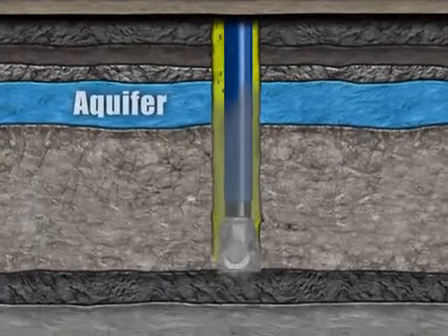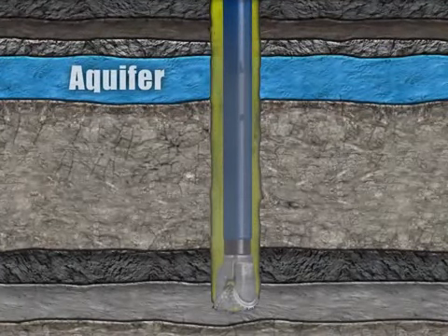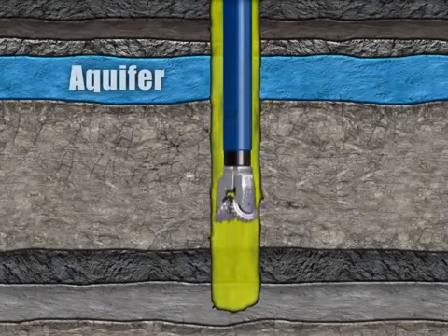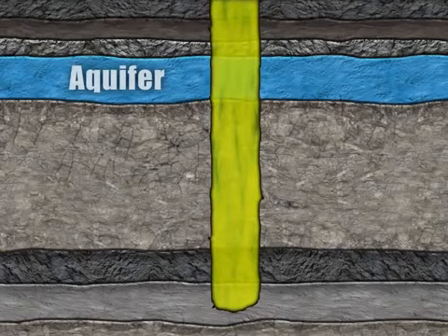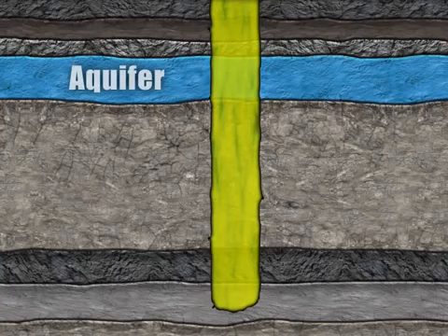Once the surface section of the well is drilled, the drill pipe is pulled out of the hole in order to lay the casing. This is done for environmental reasons, to hydraulically seal the formation layers containing aquifers from the flowing hydrocarbons later on, once the well is completed.